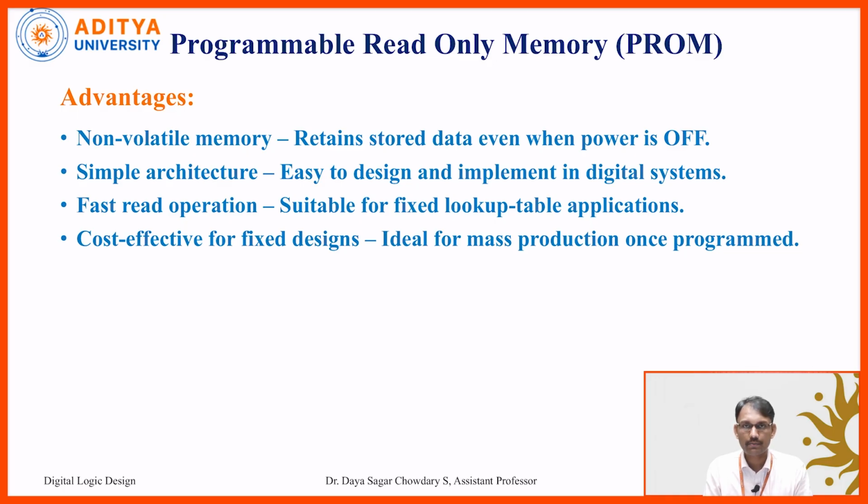So the field programmable gate array concept. That structure itself indicates one decoder, one XOR gate, one AND gate. All this combination we call a lookup table. We simply shortcut it as LUT. And these LUTs are used particularly in FPGAs. So cost effective for fixed designs, that means ideal for mass production once programmed.